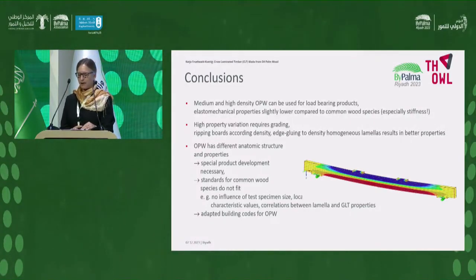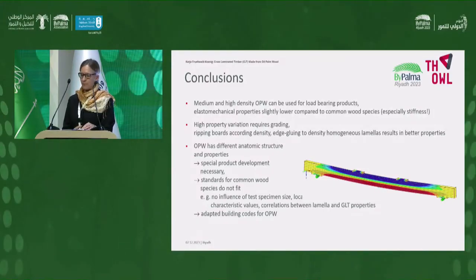The high variation of the oil palm wood's properties requires grading, for example, according to the density. The strength grading according to the density and the defined density limit values in the study are reasonable in principle. Designing beams with lamellar positions according to their density has a significant influence on the properties. Ripping boards according to their density into stripes and edge gluing these stripes to density homogeneous lamellas results in higher MOR and MOE values.